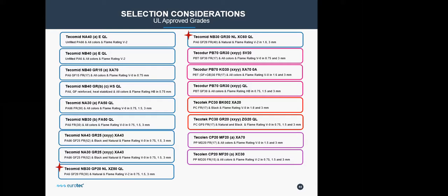One of the important standards for plastic material is UL 94, that is also known the standard for safety of flammability of plastic materials for parts in devices and appliance testing. The standard determines the material's tendency to either extinguish or spread the flame once the specimen has been ignited. Conformity of this standard is very important for electrical and electronic industry. As you can see, we have many UL 94 certificated grades. We are willing to obtain UL certificate according to customer demand and annual consumption information.